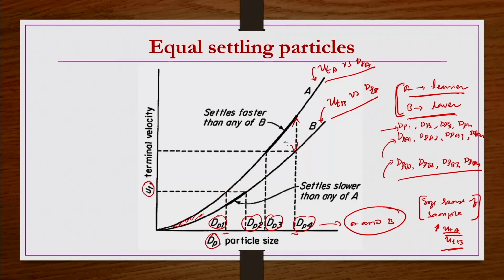The second one is, how do you separate these particles when you are mixing them in a liquid, and the liquid has a density lower than both materials? We want the material to settle in a classifier in such a way that the particles having the largest settling velocity are at the bottom, and the particles having the lowest settling velocity form the top layers, and then the liquid is above that. We do not want it like in a sink and float.